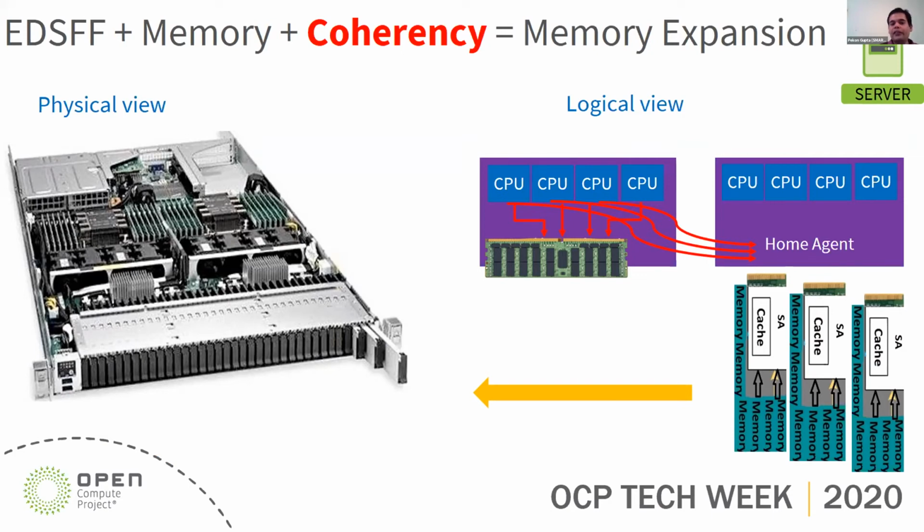They have their own packet structure, which is optimized for memory load and store performances. So what you get is a high performance from a serial interface and a low latency from a cache coherent interconnect. Combining the two in an EDSFF form factor makes it a very good solution for a memory expansion device. So this is our goal here, to have an EDSFF memory module which can be used as a memory expansion device and augment a DDR bus interface, which is currently saturated.